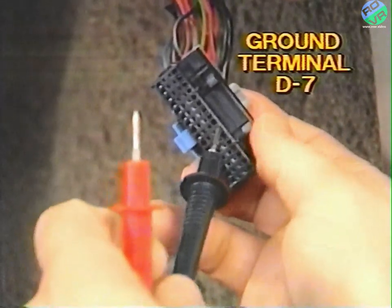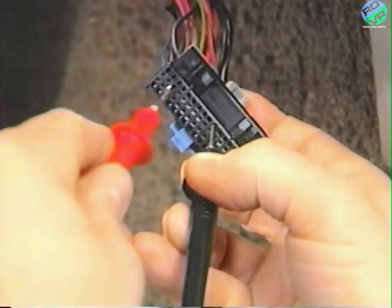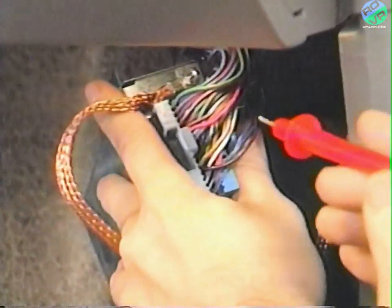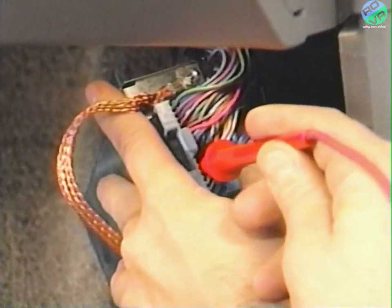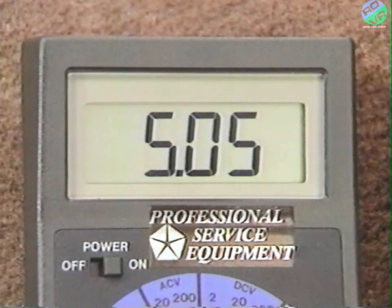You can do this by using the terminal as a ground for the voltmeter while probing a known good battery feed wire with a voltmeter positive lead. Finally, check the 5-volt reference signal wire from the ACM to the switch assembly. This is connected to terminal E3 of the switch assembly.